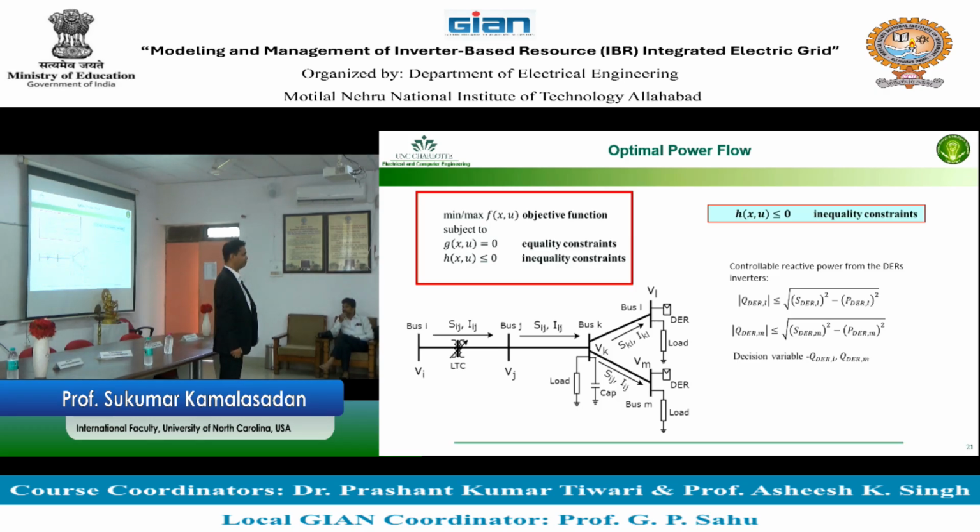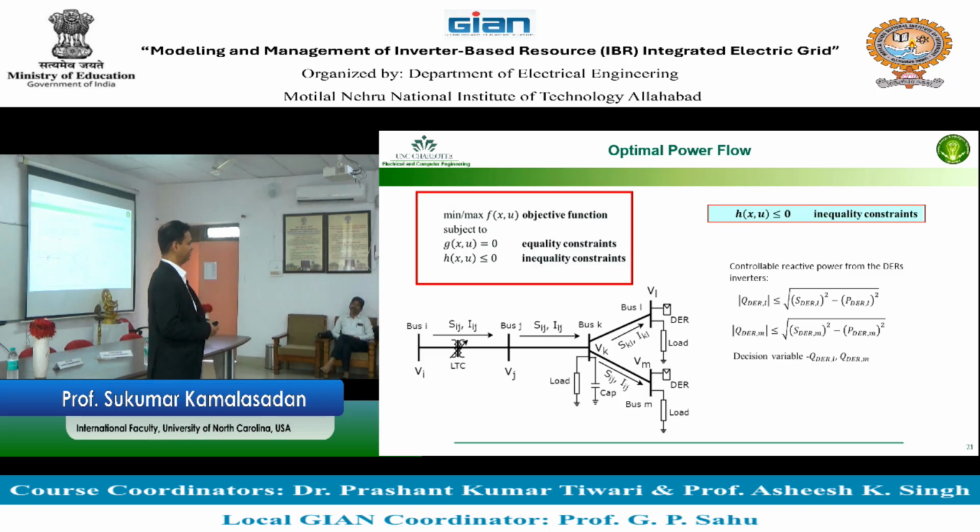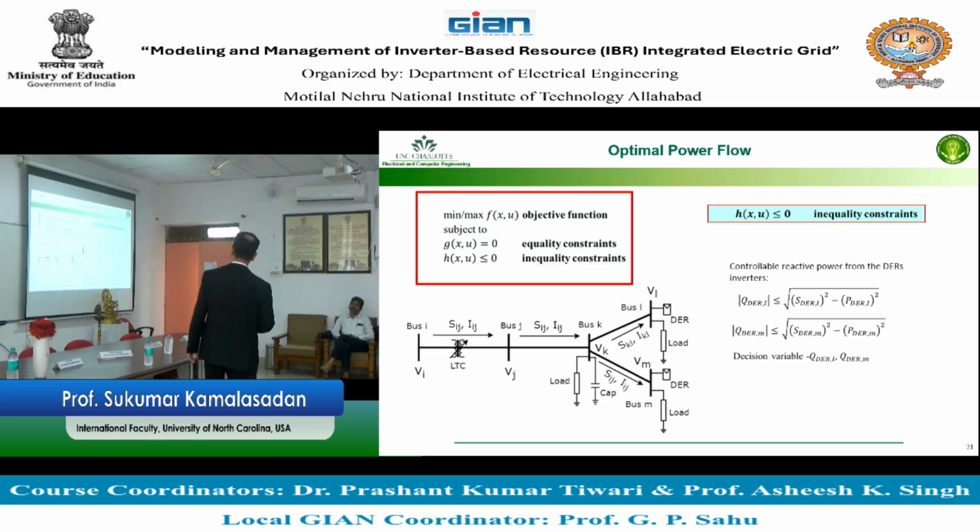If the capacity of the inverter is 7 MVA and the active power which you are pushing through this inverter is only 250 kW, well, you will get free reactive power. Why is it free? We talked about the story of being free. No inductor, no capacitor. It is only the difference between the angle of the voltage and the angle of the current, basically. And that's what we consume from the reactive-power-controllable DER, and the decision variable is this set point.